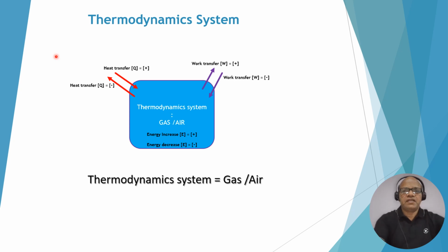the gas. As per the sign convention, if heat is transferred into the system, that means into the gas, it is considered positive, and when heat is taken from the system it is considered negative. Similarly, when work is done by the gas or by the system it is considered positive. When work is done on the system it is considered negative.